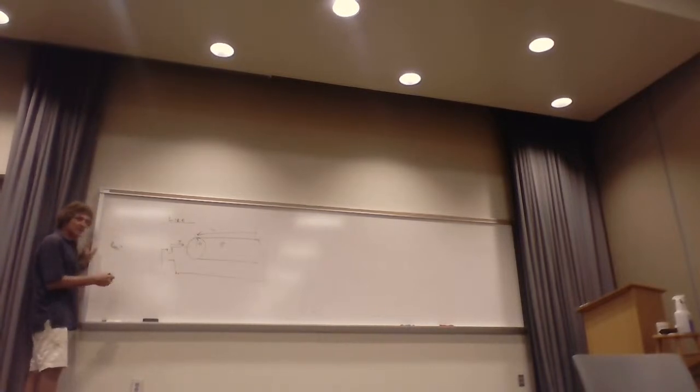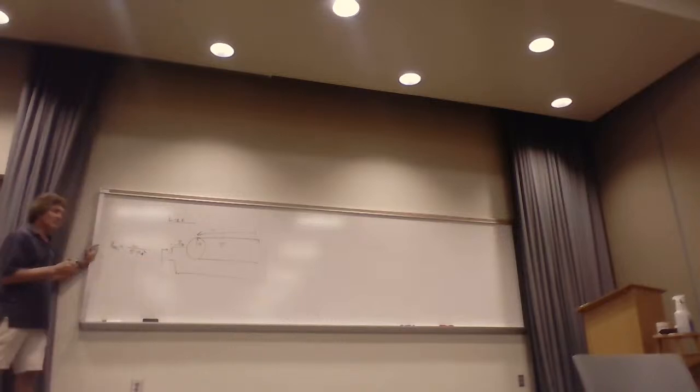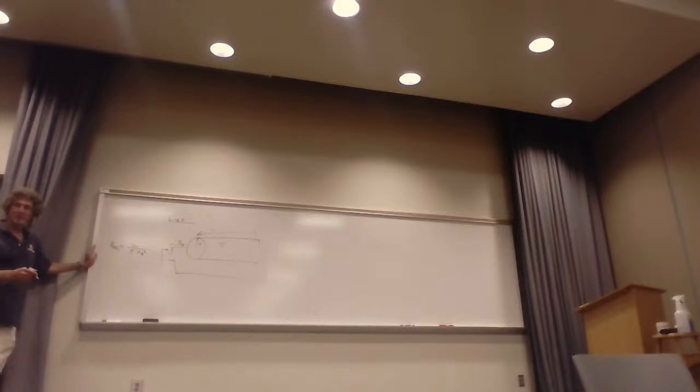At the end of the day, I just did this in the other class, you get the resistance is proportional to the length, inversely proportional to the conductivity, and inversely proportional to the cross-sectional area. Here it's pi a squared. Do y'all remember doing this? We did it here too, didn't we? Didn't we do high frequency wires? We did skin depth, right? Now, what happens when you get up in frequency?